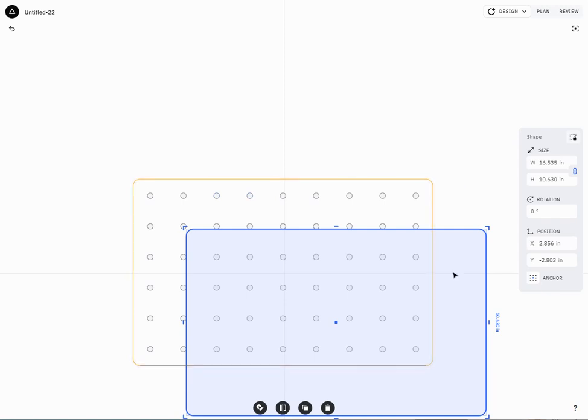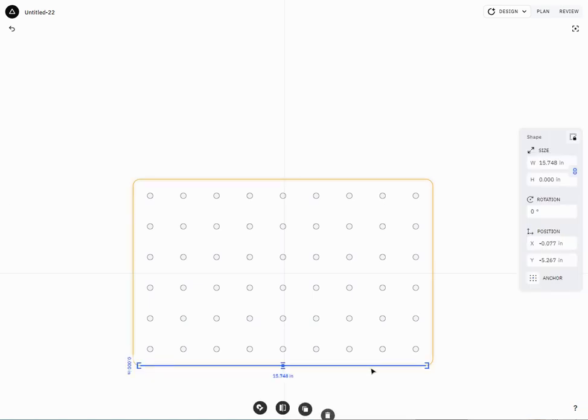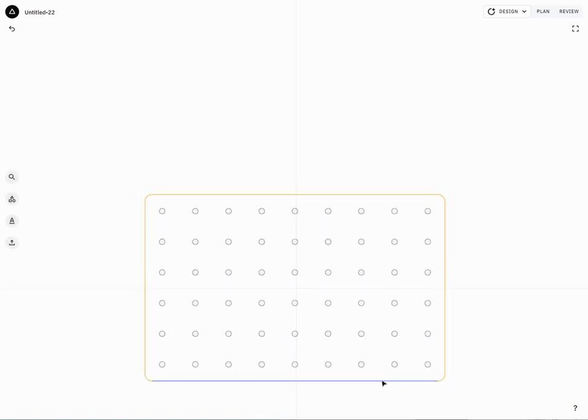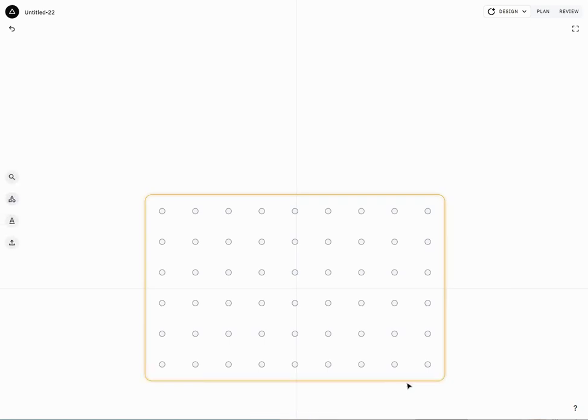So that's basically what we're going to try and do: find any duplicates and delete them. So I'm going to delete that, and then I see down here there's pure orange or yellow, and then there's a little black element here. So that's showing me there's another duplicate. So let's just delete that. I'm just hitting the delete key on the keyboard. So now the perimeter looks clean. There's no black or selected blue elements, just that orange.